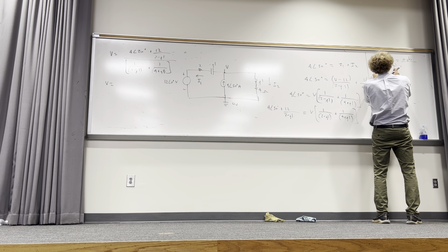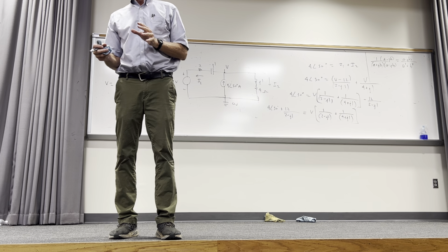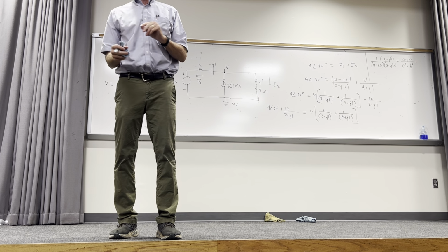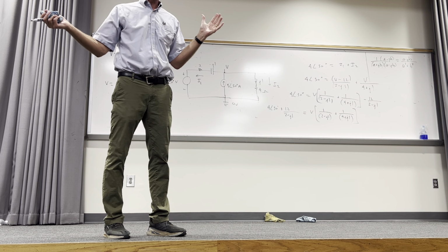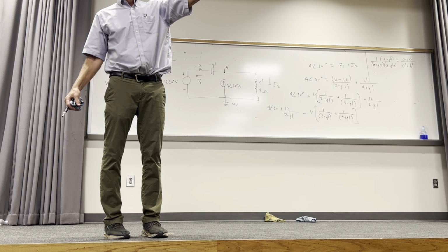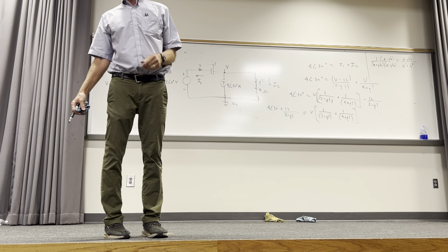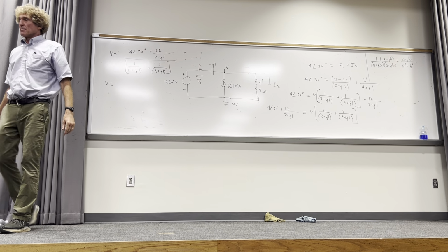Then you get J times minus J, well that's really minus 1 times minus 1. So it's going to be A squared plus B squared. Now that will break down to a real and imaginary part, because you just have A squared plus B squared in the bottom. So it's A over A squared plus B squared, and then you're going to have minus J over A squared plus B squared, if you want to do it that way. That's called the complex conjugate. How many have heard of this before? That's one method. I mean, people do it all different ways. Regardless of how you do it, you're going to have to be able to do this and do it efficiently. So I want to make sure you get your calculators out, and if you do this, what do you get for V? Magnitude and angle.